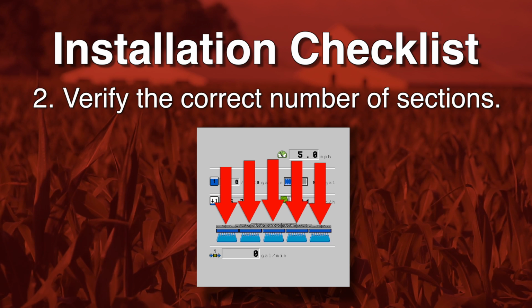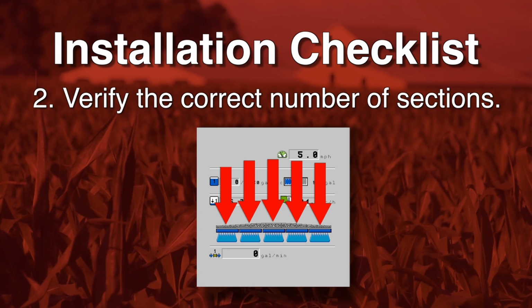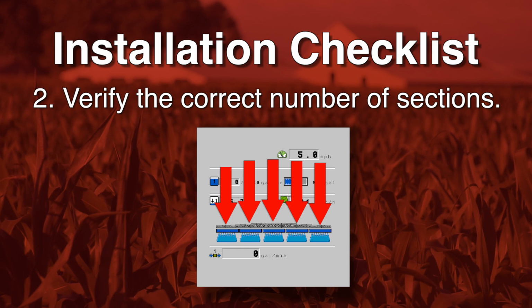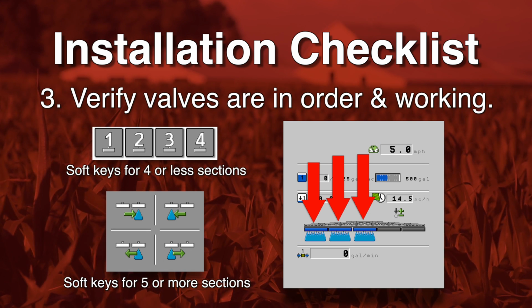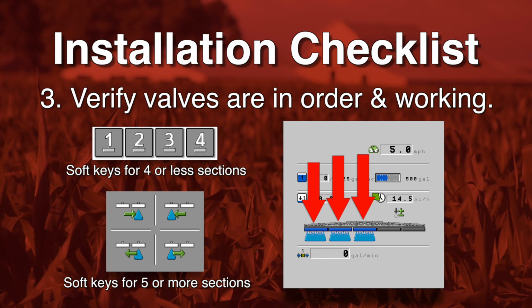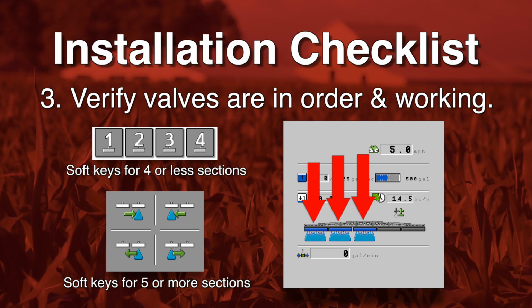Secondly, verify that you have the correct number of sections by counting the blue bars on the universal terminal. If you are running 5 sections, you should see 5 blue sections on the display. Thirdly, double check that your valves are in the correct order and are functioning correctly. Use the soft key buttons on the universal terminal to verify this. Visually and/or audibly confirm that the valves open and close with the use of the display.